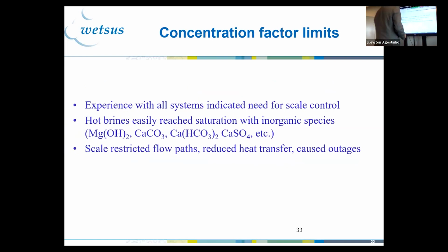So going very high with your recovery or your concentration is normally not a good idea. Experience with all systems indicates the need for scale control, of course, due to that. And as I told you, these guys are not really, do you remember, these guys are not really the most concentrated ones, right? We did see which one of these comes after the sodium chloride.